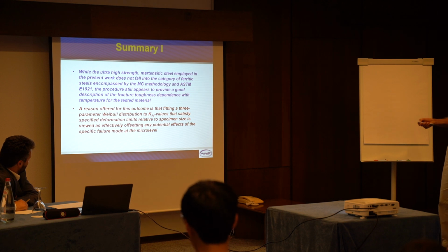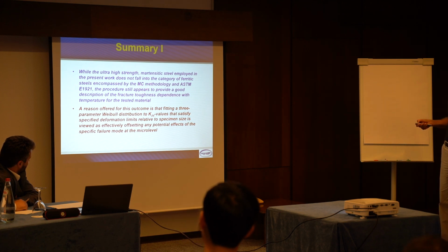While the tested steel, a martensitic steel, does not fall within the requirements of the ASTM standard, the procedure still appears to provide a very good description of toughness with temperature.